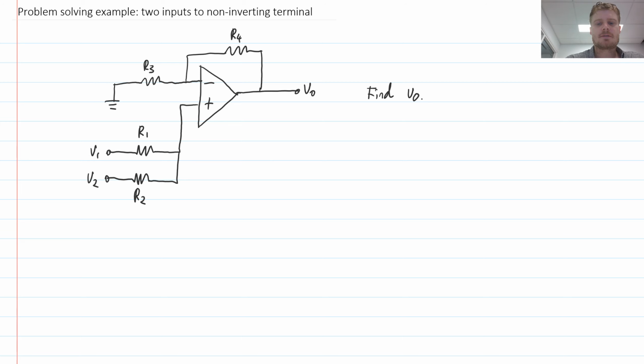But anyway, let's run through our steps. First of all, we need to make sure that we have negative feedback. And I look at this circuit and I see, yes, there is a negative feedback path. So our output is connected through R4 back into our inverting terminal. So it's always the inverting terminal that we're checking for. So yes, negative feedback. Therefore, we can proceed with this method.